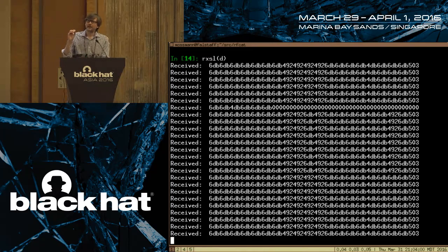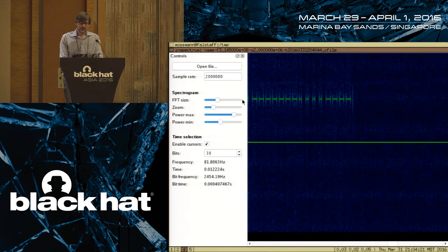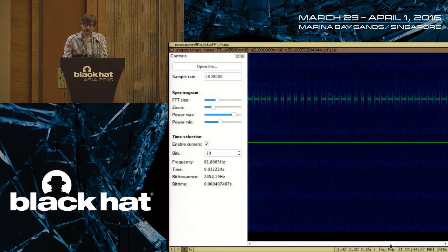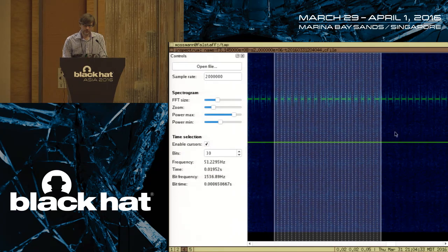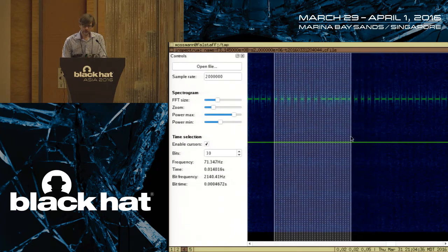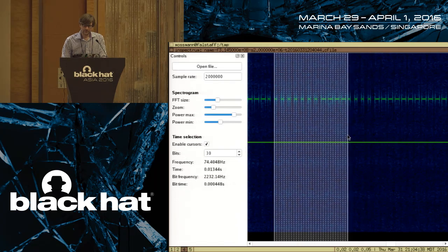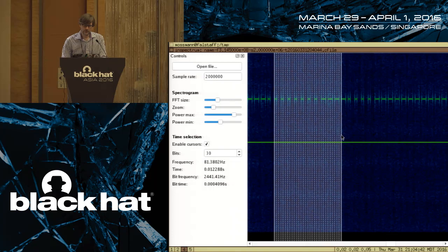Now what I want to do is actually decode the pulse width modulation. So instead of 110, 110, 110, I want to see that that's long, long, long, and 100 should be short. So I'm going to take those long pulses and represent them as a 1, and take the short pulses and represent them as a 0, or the other way around. Now, one way to think of that is, if I were to, let's say, use my cursor here and line things up, you can see that, is that about right? Or there? There we go.